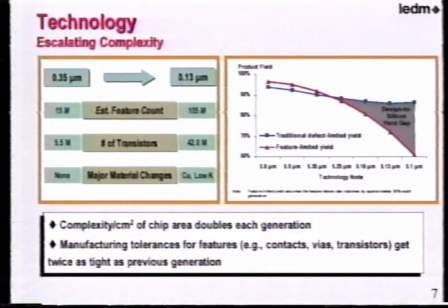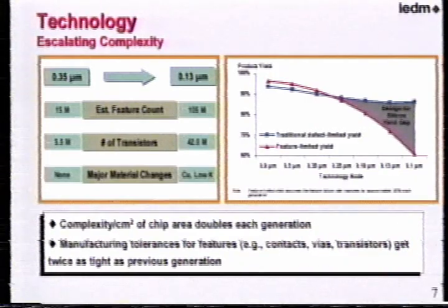Because when we talk about this in more detail, it will become obvious that it's not just the number of contacts and vias, the number of holes that you have in your interconnect. It matters how they're placed within the design and what environment they're seeing. That's a big, big problem for the systematic portion of the yield, which I'll come to. And then finally, we're getting new materials, which I talked about.